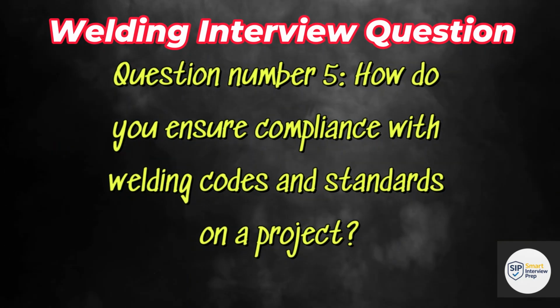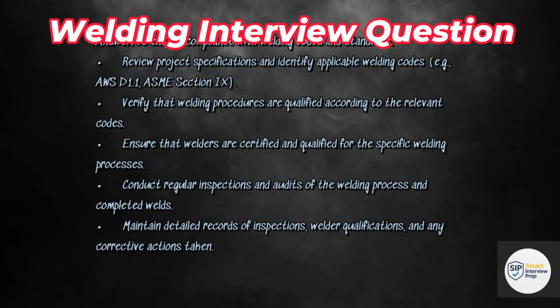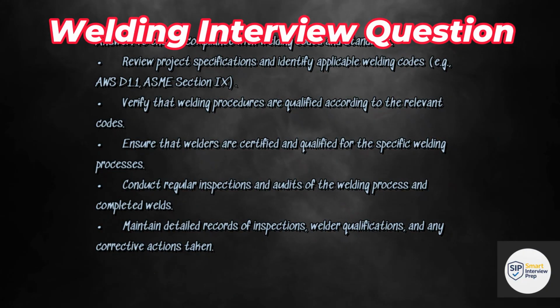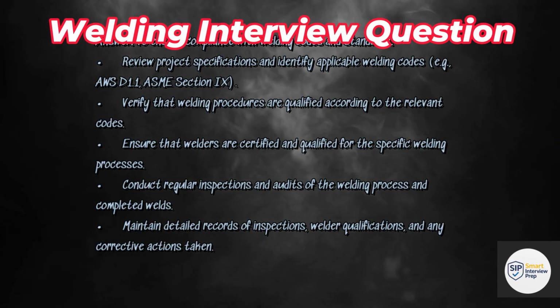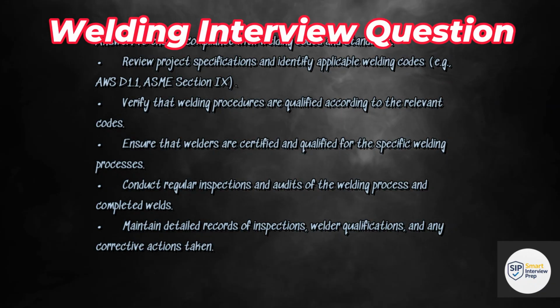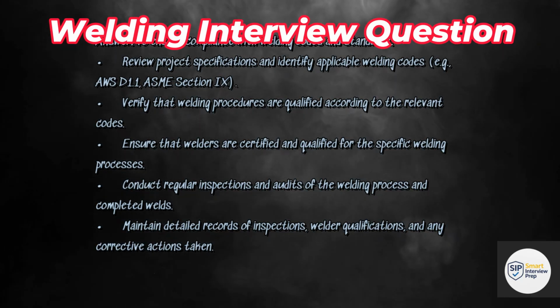How do you ensure compliance with welding codes and standards on a project? Answer. To ensure compliance with welding codes and standards, review project specifications and identify applicable welding codes, for example, AWS D1.1, ASME Section 9. Verify that welding procedures are qualified according to the relevant codes.